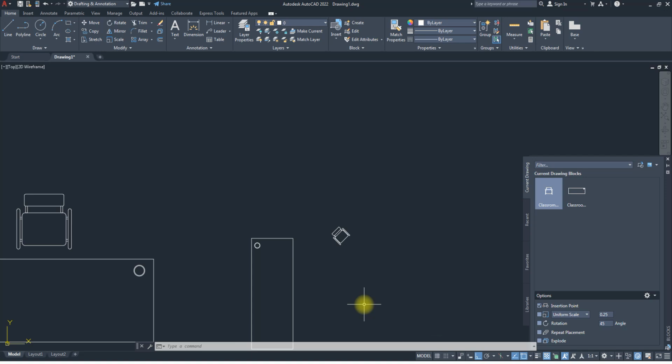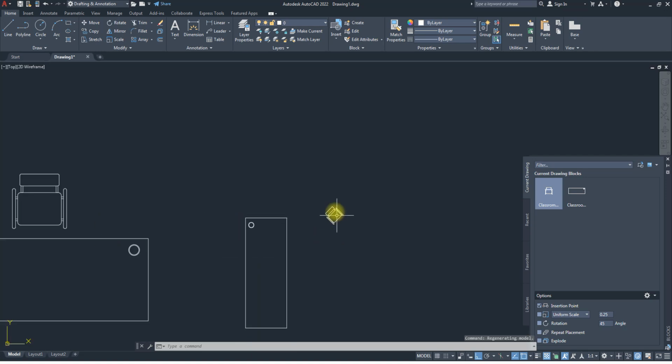So that's the advantage this one has over bringing, because really, when you create your block, any drawing you are bringing it to may have a different scale. If you just start bringing it in, it may appear too small or too large. Which is why this option is there for us to scale on inserting it. But that doesn't mean if you insert it, you can't use your normal scale command. You can still use your normal scale command, but I should be able to do it before bringing it into the scene. So that's why the shortcut is important.